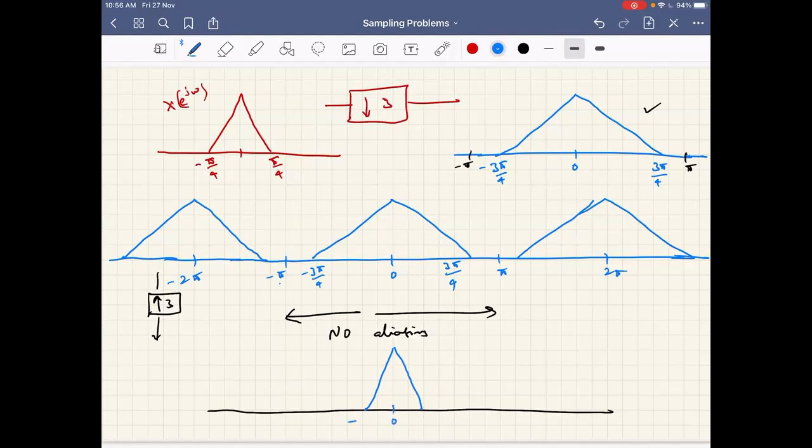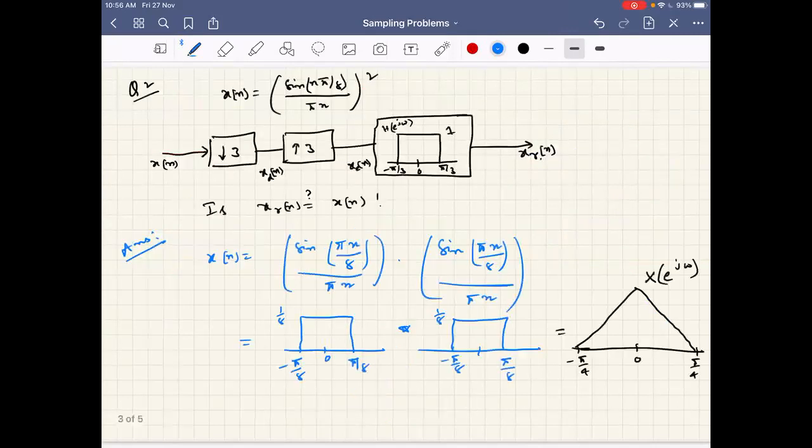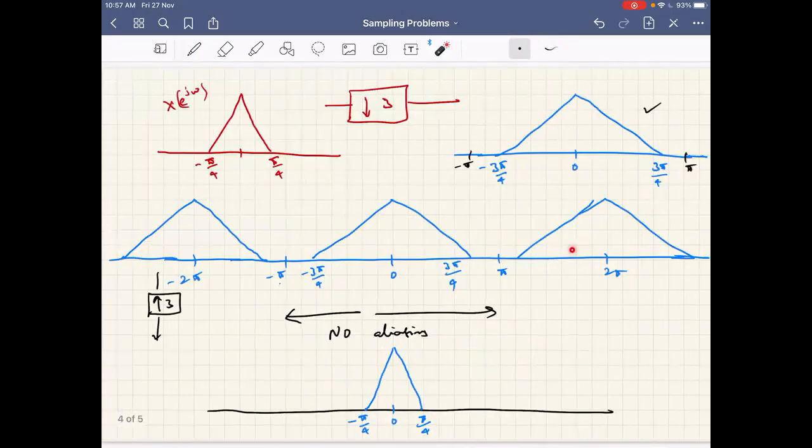Okay, now it is minus pi by 4. So it comes back again to minus pi by 4 and pi by 4. And where will be the next one? That is important now. Because see, there is a filter here. After this step, they have given a filter from minus pi by 3 to pi by 3. In some cases, if they give from minus pi by 4 to pi by 4, or minus pi by 2 to pi by 2, then we need to see whether these spillover terms will come into the spectrum or outside it, or whether this spectrum is completely captured or not.